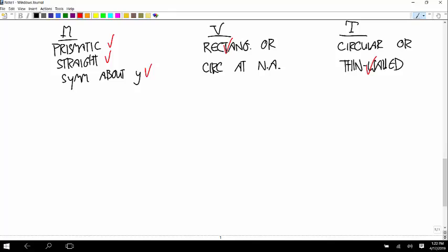Okay. So first, calculate the stress due to tension. So it's an x stress that's equal to the tension over the cross-sectional area. And the cross-sectional area is, so we can do it as the outer area minus the inner area.